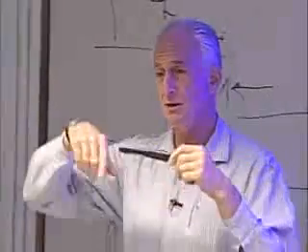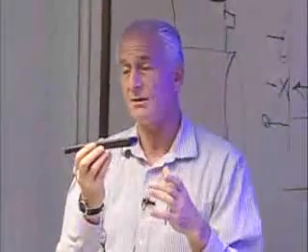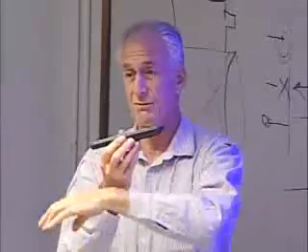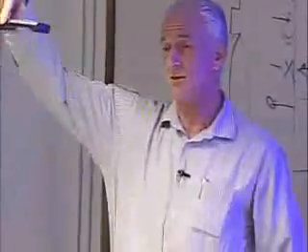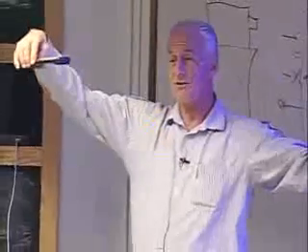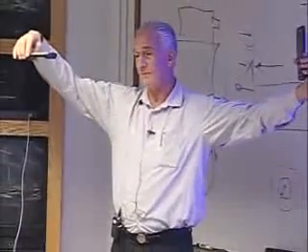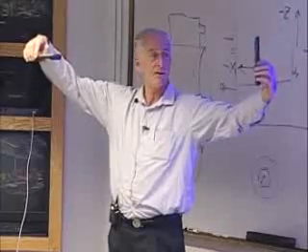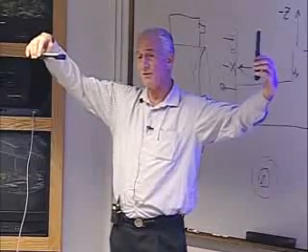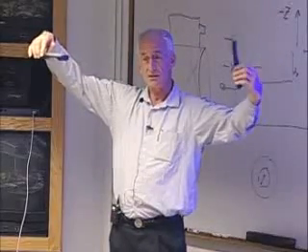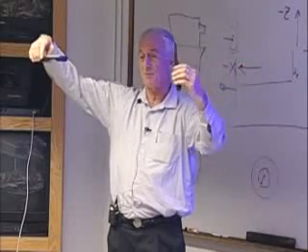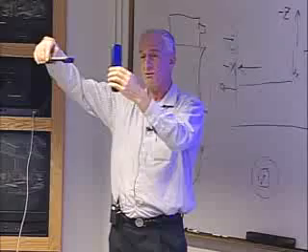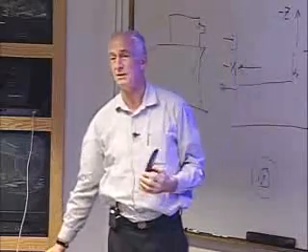Although, because all of the verniers are essentially downward firing, if you are, for instance, station keeping, if here's the space station and you're in the same orbit, but say, half a mile in front of it, now you're station keeping using your vernier thrusters, typically that does give you, after a while, a little bit of propulsive maneuver which pushes you in, so you have to compensate for that.